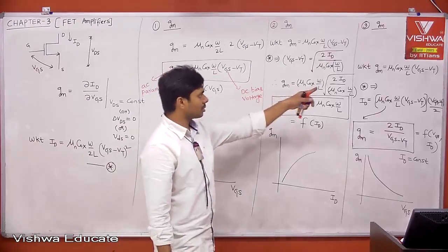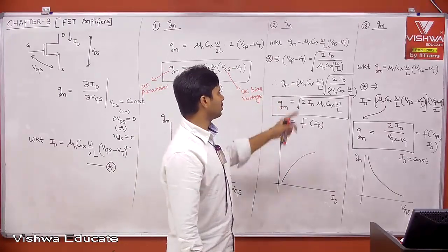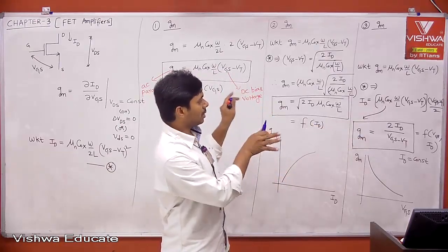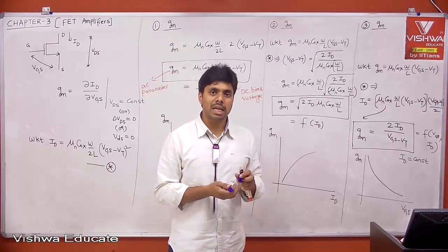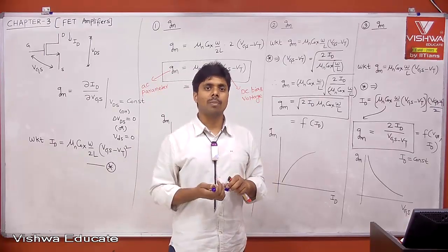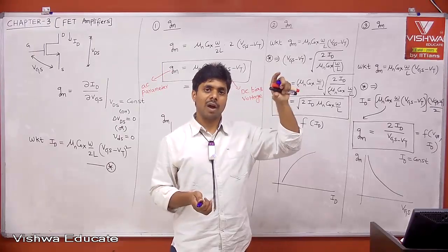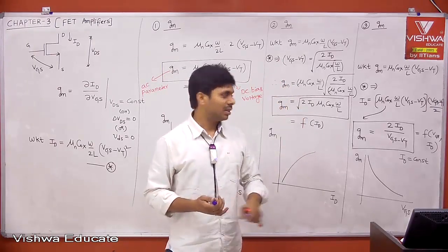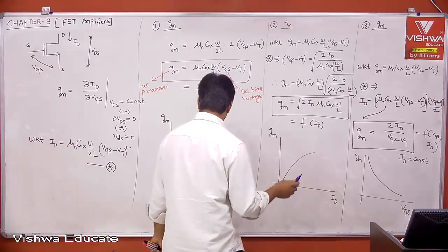But we did not see these circuits actually. Mathematically it is nothing but writing GM in terms of ID, and then in terms of ID and VGS. Mathematically these are all straightforward, but qualitatively they are not the same as whatever we had seen. Like the common source amplifier with passive load, passive RD. Instead of RD, if you put a current source where the output current is constant, then these two will come into the picture. If time permits, I will try to explain.